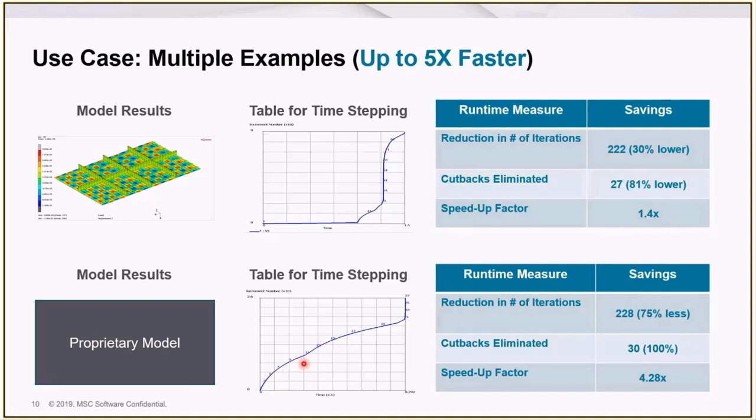And you can see there was a ramp up. There's initially a little bit of a fast ramp up, a number of smaller increments followed by regular size, and then we got to very, very small increment sizes. Based on what we're representing here, if you have a very steep curve, it means you're taking very, very small increment sizes because the time difference is very small. So we had obviously a very highly nonlinear event here, and maybe a smaller nonlinear event in the beginning.